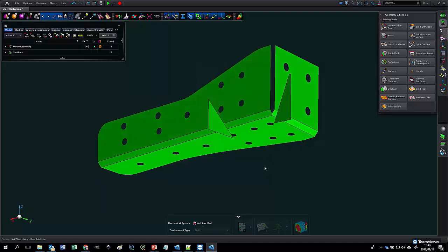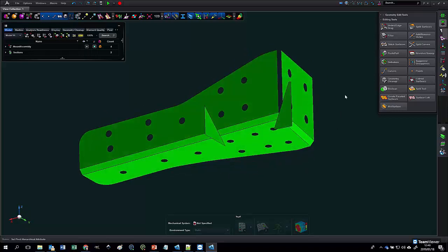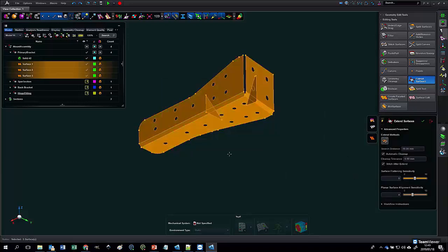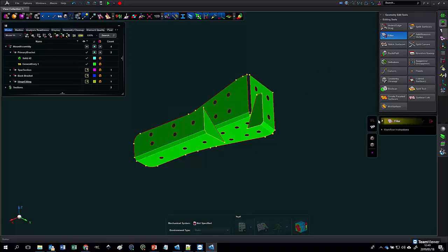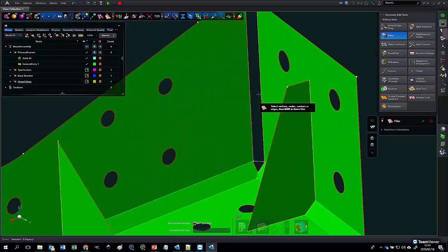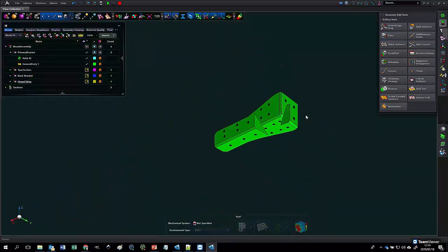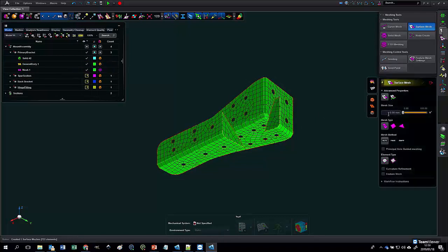One being the auto extend tool. Now this is, remember, if you like to use the stitched method. Otherwise, if you want to use the glued method, you could most probably leave these gaps. Just use your auto extend tool. Find a larger gap. Select all your bodies and have them automatically extend. You can also create surfaces using the filler tool. Create bodies manually like that, or automatically close holes like that over there. And then you have a stitched body that you can now mesh.